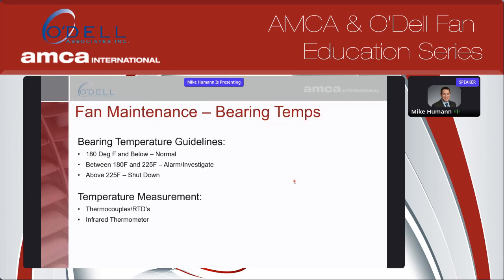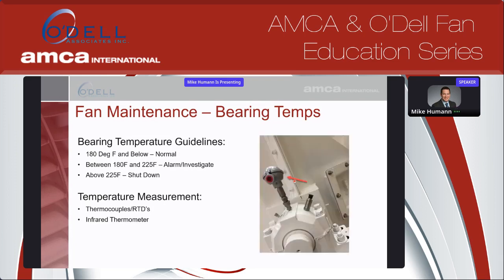A couple ways to measure temperature in fan bearings or in motor bearings. You do have thermocouples and RTDs. Here's an example on the right-hand side of a bearing RTD. That instrument actually has a little probe bedded inside the bearing near the outer race, and that helps monitor the internal temperatures of the bearings.